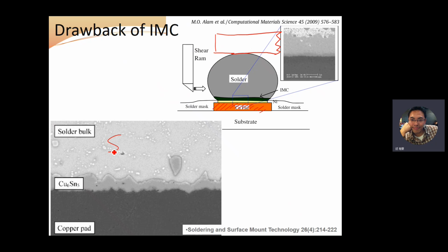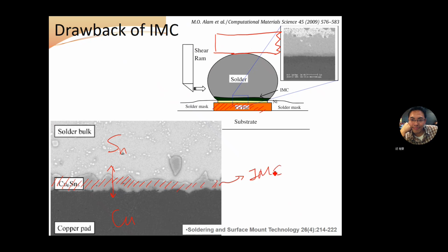So it's tin, right? The major component of the solder is tin, and the bottom connecting pad is copper, right? So they must have a diffusion reaction in between during this thermal cycle. And gradually, this intermetallic compound between the solder and copper pad must form here. This is the intermetallic. Its hardness is close to ceramics.